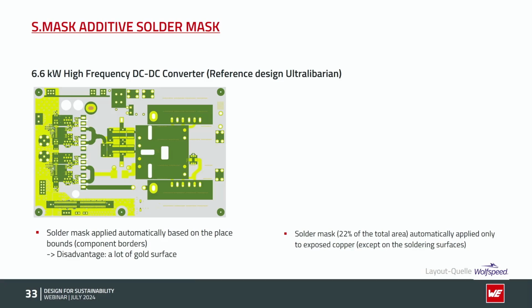What else is possible? Why is a PCB today green? Because, as I mentioned, you cover everything with solder mask and remove only the areas where you need it. With inkjet, we can turn the idea around and just apply the solder mask where you need it. That's what we have done here with this example of a DC-DC converter, where we only printed a small ring around the through holes, for example, to avoid the areas, and the white stuff is just bare